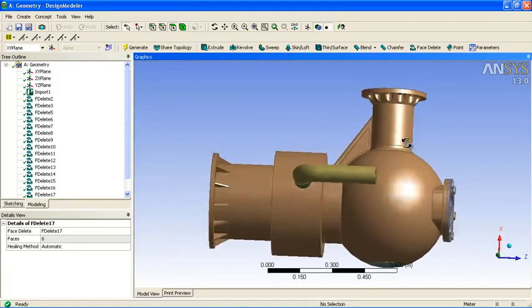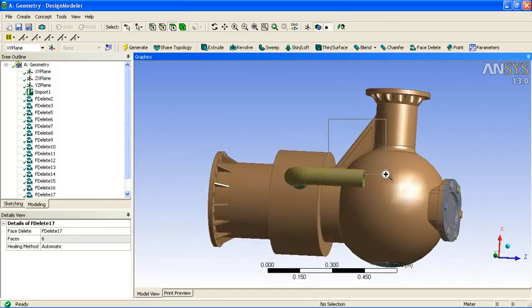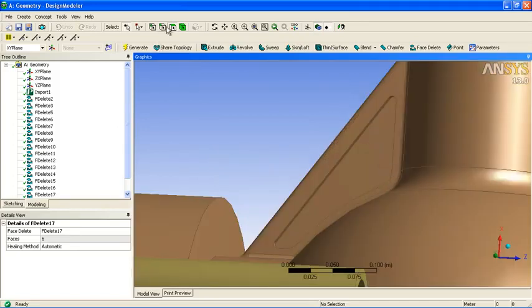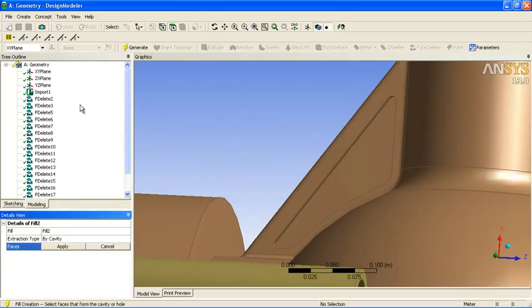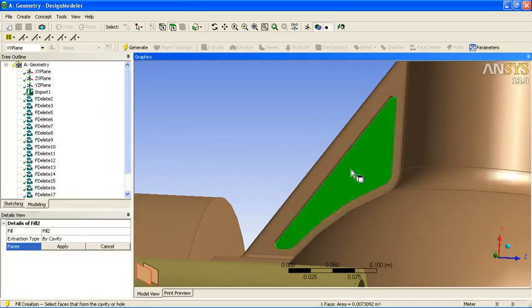And finally, we can look at adding information instead of removing information. So where we have this pocket, we can generate a fill volume. So we simply select the surfaces that describe the volume. So the lower face and the surrounding surfaces.